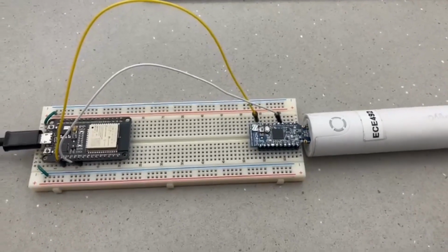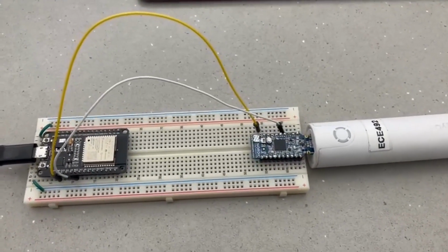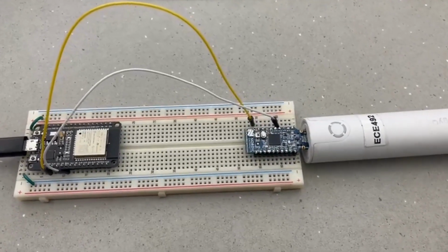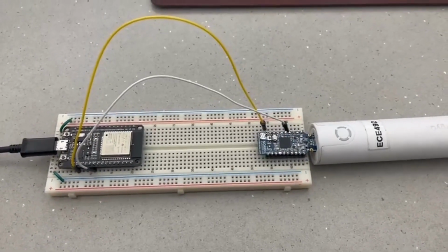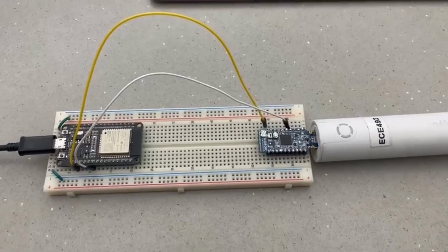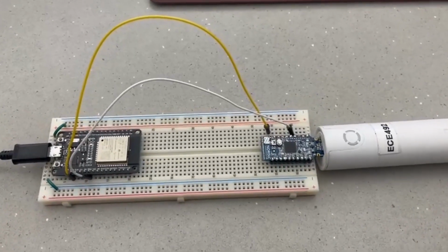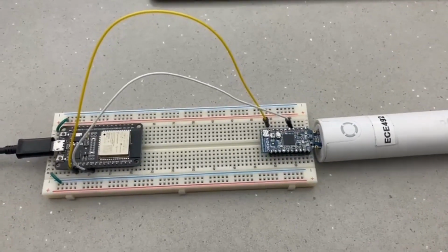and it's responsible for running the BLE observer code. And when it comes to the firmware side, it runs a Zephyr OS, and the Zephyr OS allows us to abstract away most of the advertisement packets that are being observed by the Nordic chip, and allows us to focus on the logic instead of going through each communication protocol when it comes to Bluetooth Low Energy.